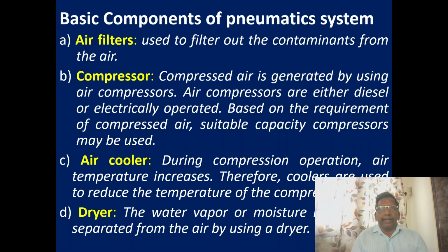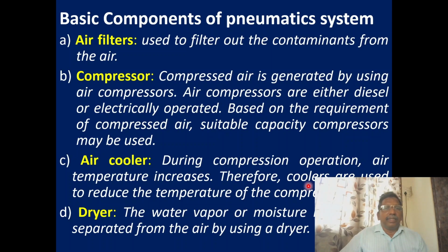In the pneumatic system we have air filters. They are kept at the inlet of the compressor. We have to filter the contaminants in the air, micro-level or nano-level particles. Then we have to remove the moisture content, so we need a dryer also.